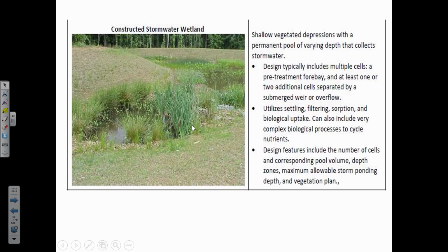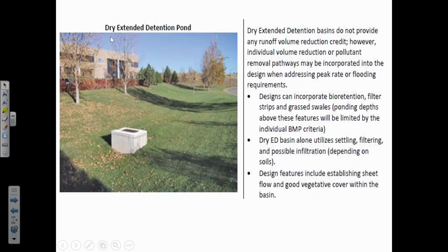But there can be some improvements in the chemical quality of water, because bacteria that naturally will grow in the water can remove some of the biological contaminants that may come from the runoff, and even the chemical pollutants can be taken up by plants like cattails, and so you're improving the water quality, and the water level may fluctuate in that pond and allow you to have some delay before the water has to go elsewhere into a stream.